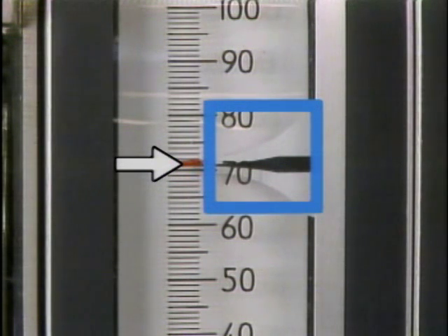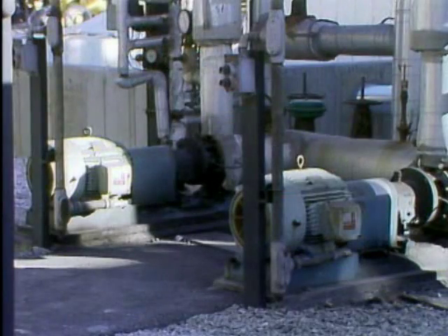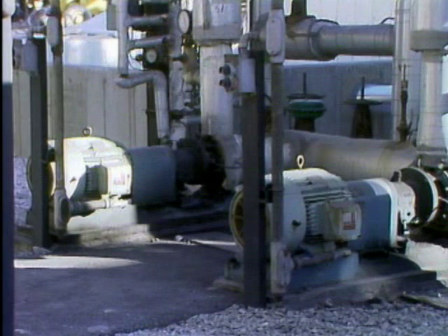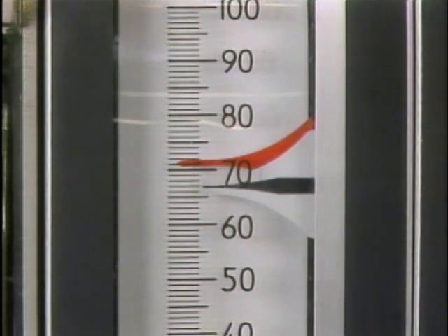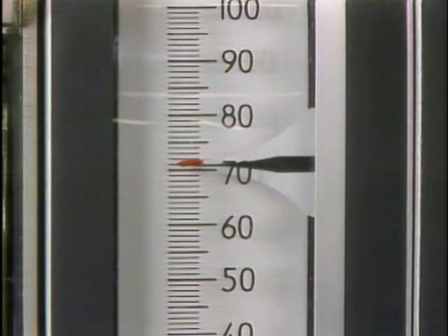Otherwise, rapid shifts in control action called bumps can occur. Bumps can adversely affect process operations, and they can sometimes damage equipment. To avoid bumps, the values of the process variable and set point should be equalized before a switch is made from manual to auto. A bumpless transfer can be done in one of two ways.